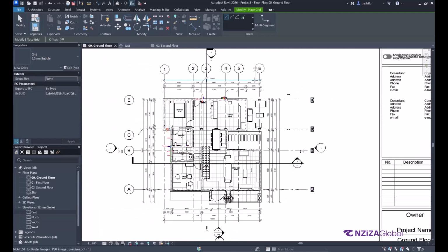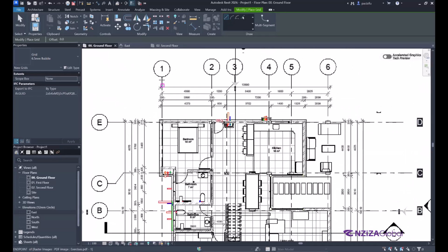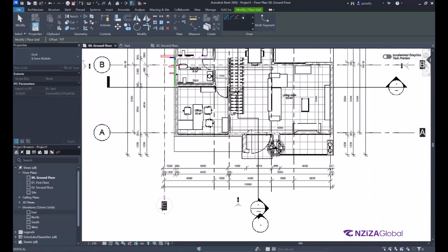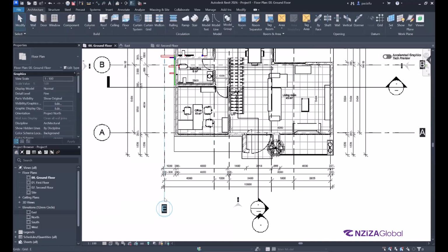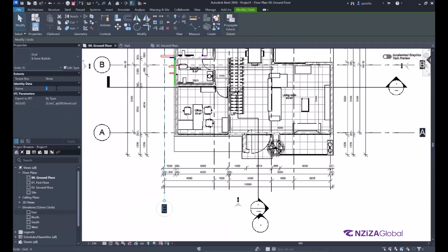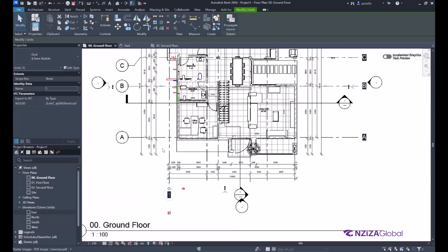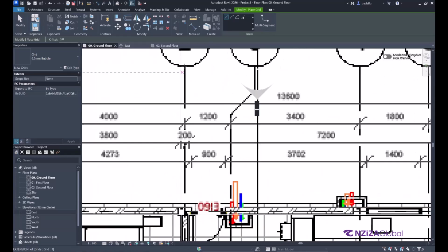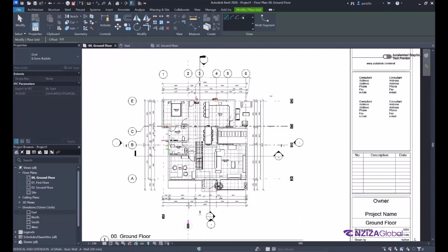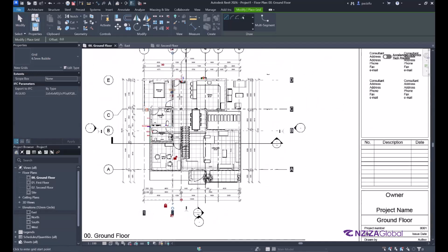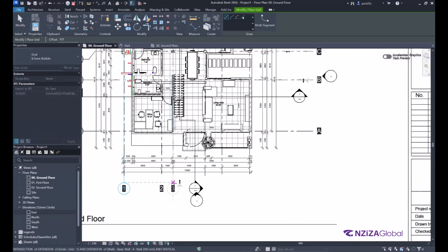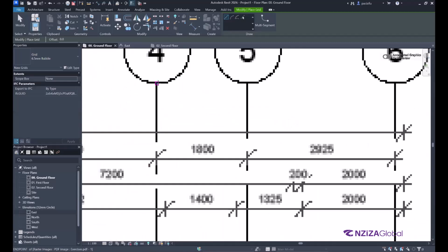So now, when I go for numbering, I will start as normal. It will show me that it is going to continue on E. Then I will select this grid for E. I will change it into 1. After changing it to 1, then I go for create similar. It will now continue by 2, 3, 4.